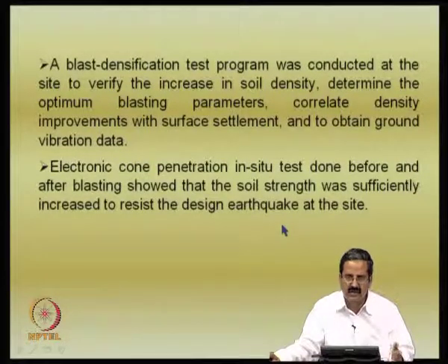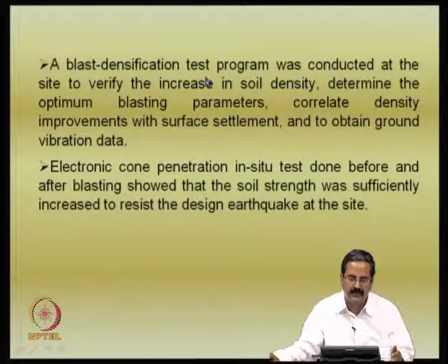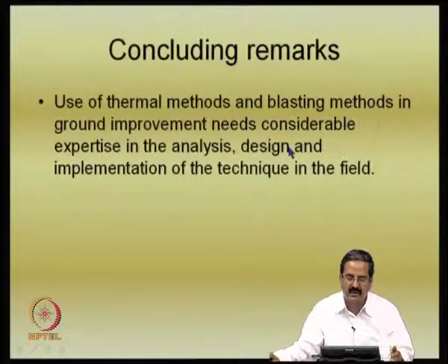Once they were able to achieve this, they were able to confirm it with field observations of CPT tests, and they had enough soil data to confirm that their design is correct. Finally they were successful in conducting the blast densification program, and as I mentioned, it has been quite cost effective compared to even the standard dynamic compaction methods and other methods of ground improvement.